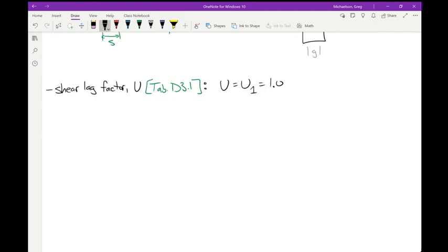In this instance, because all of the cross-sectional elements are connected, we can go ahead and take case 1 to be the one that applies. If it was only one leg, case 2, because case 2 applies when only some of the cross-sectional elements are connected. So really, case 1 and case 2 are the ideal ones that you're going to want to refer to first. So now what we can do is assess our limit states.